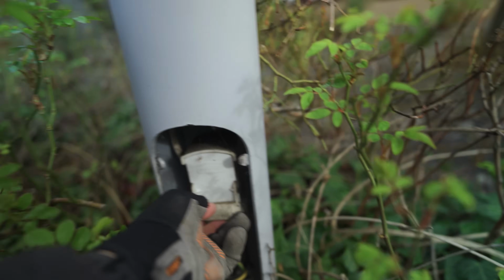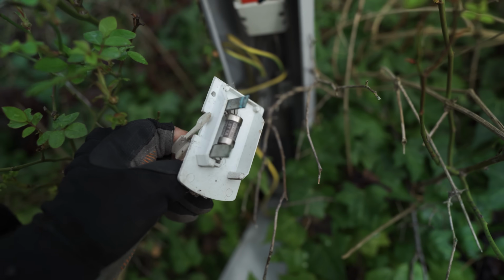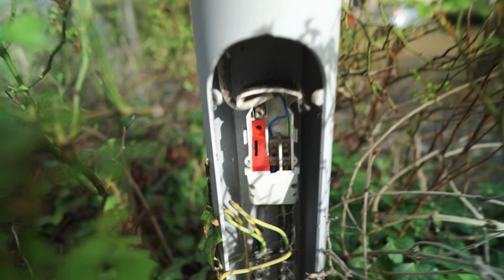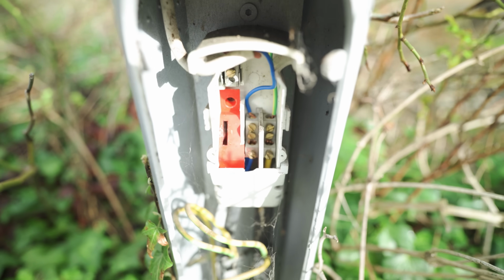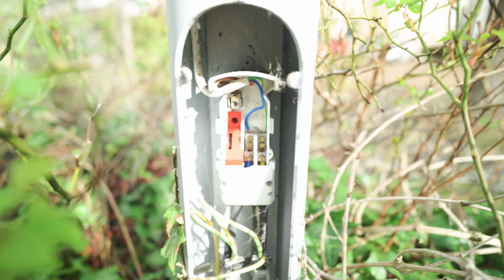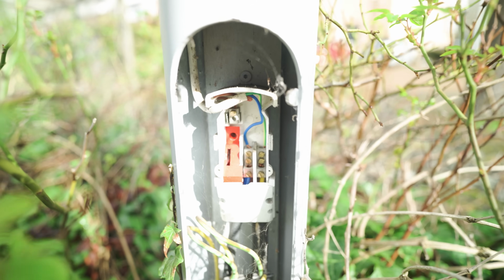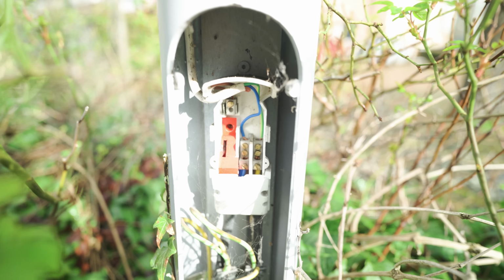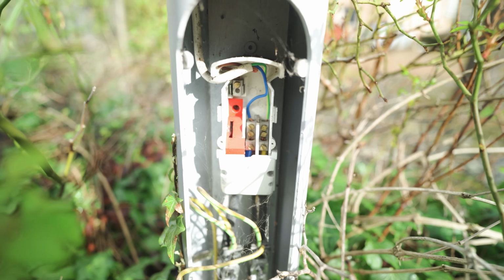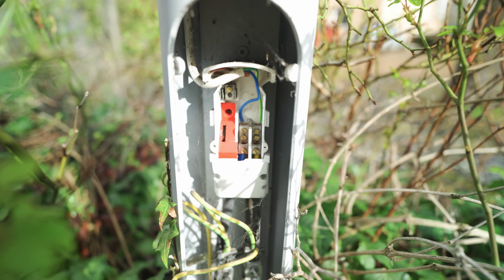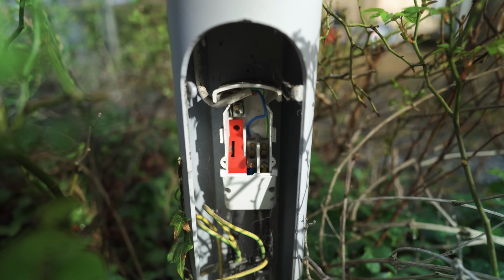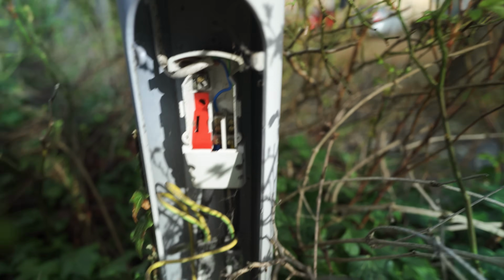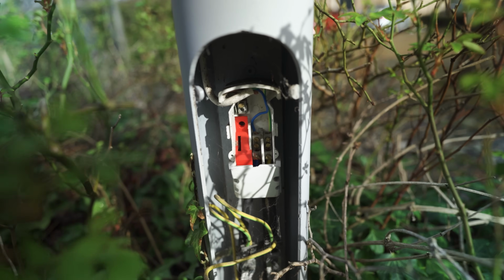Drop that out. Lift that. Pull that out. There's our fuse. Tiny little 6 amp. That is our holder. I mean, that connection there, bloody terrible. That neutral is barely put away. Everything else seems okay. And obviously if it is a neutral earth fault, I will need to go round and disconnect them all as well. Pulling the fuses won't be enough, because obviously the issue will be between neutral and earth, and they're still permanently connected. But let's get all these removed first and see what happens.